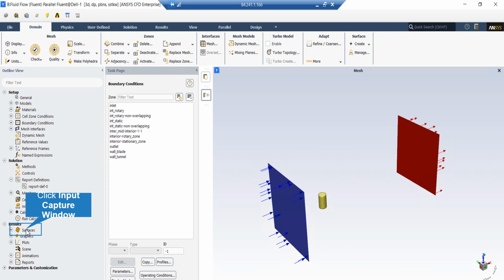regarding the pressure drag. Other parameters such as vorticity magnitude or Y plus could be further studied through our contour variables. Also in this study, we've demonstrated flow movement through the use of vectors, which is pretty informative to understand how our wind turbine guides the flow pattern.